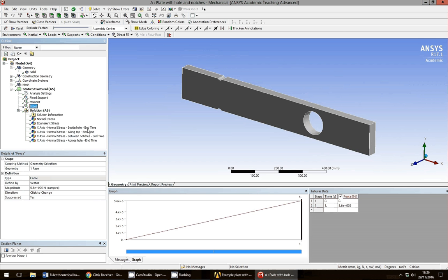The way the buckling analysis works is that you do a static structural analysis first with a particular set of loads. Then you add in the buckling analysis, and it factors up the chosen loads to see what we'll call the buckling load is, and different modes of buckling.